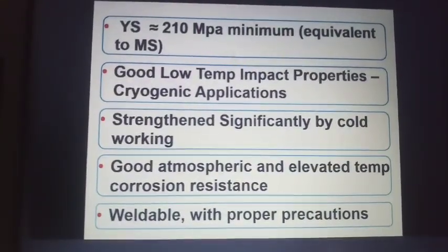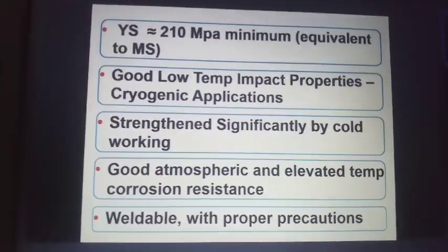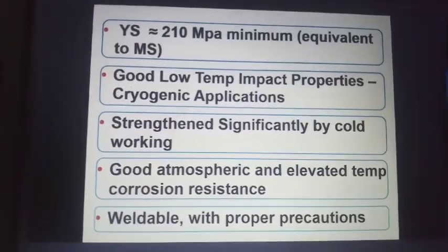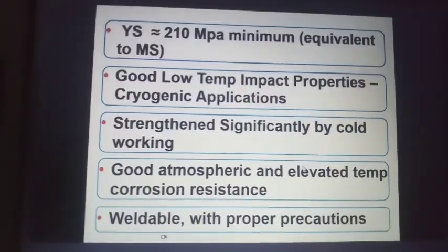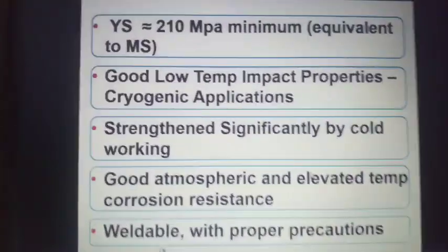Just show the values, and just show the lateral expansion in impact testing. Correct. In case of stainless steel, it is not energy, only lateral expansion.